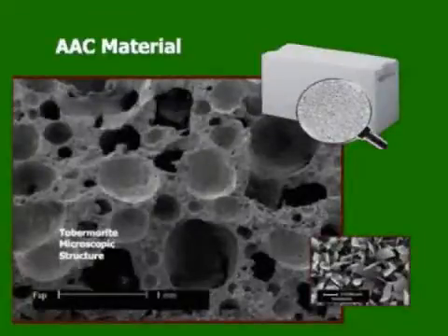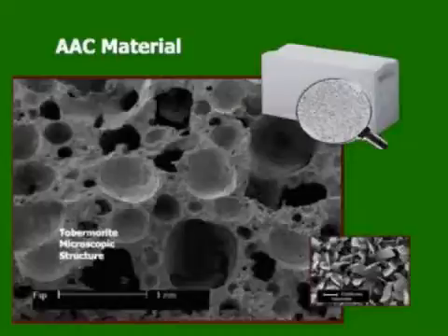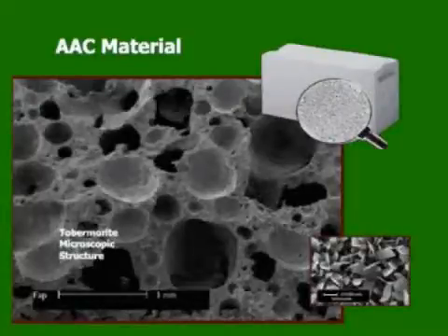The final hydration product is also called tobermorite, as seen here under a microscope. You can see numerous air pockets. However, not all are connected, which gives AAC its unique properties.